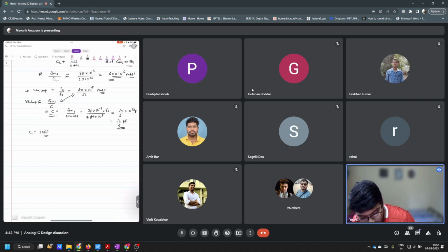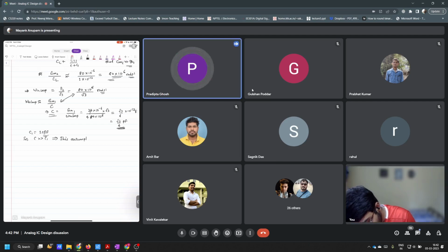This is your C, picofarad, so it's nearly 433 femtofarad. So is C much greater than C1? Yes. This assumption is justified, isn't it?